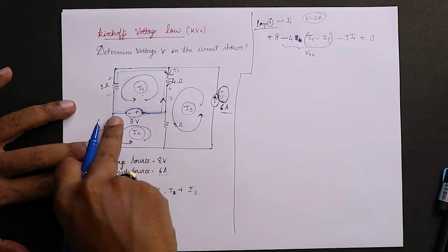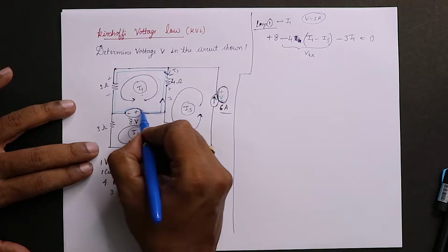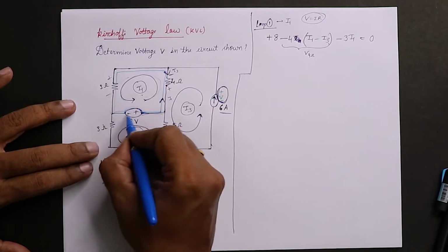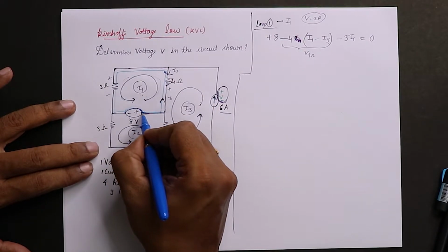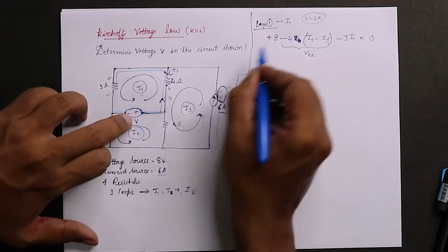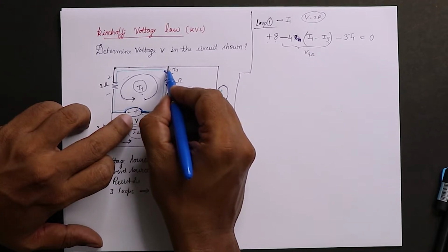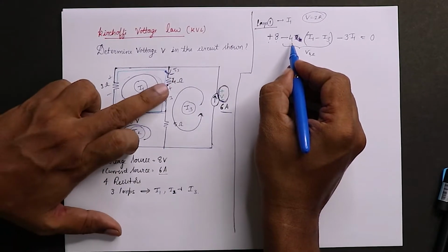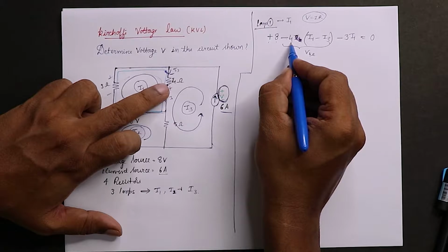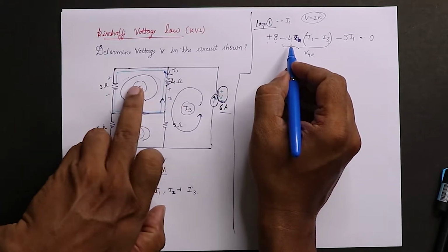I'll tell you again. I'll start from here. Current is flowing in this way, so it entered with a minus and left plus. So the leaving sign is taken plus for the direct voltage source. When it enters the resistor, it is plus, and when it is leaving, it is minus, so we take only the leaving sign, that is minus. 4 is the resistance, and the current flowing in the 4 ohms is I1 and I3, because it is in between I1 and I3.